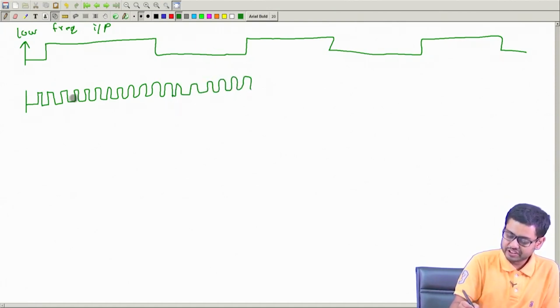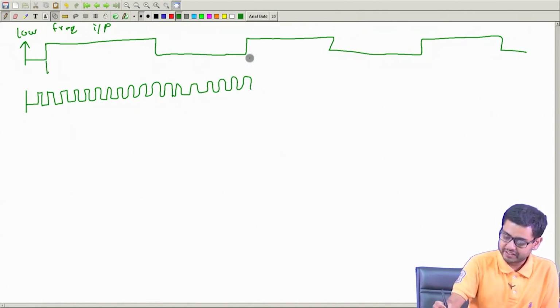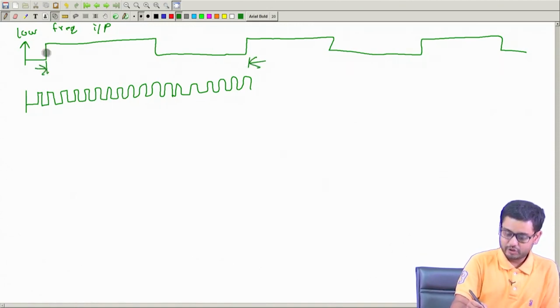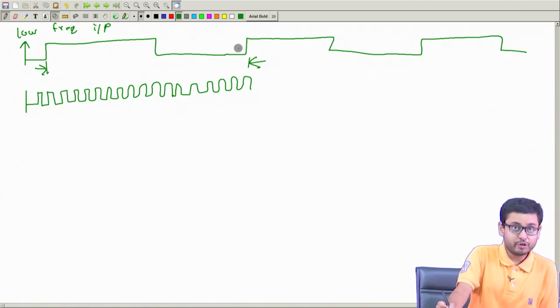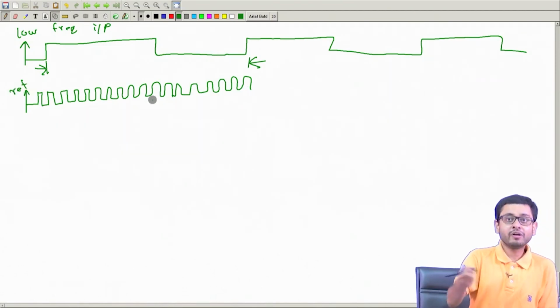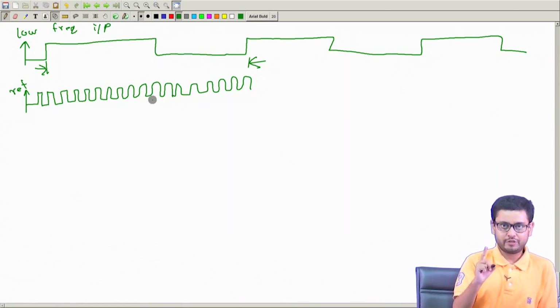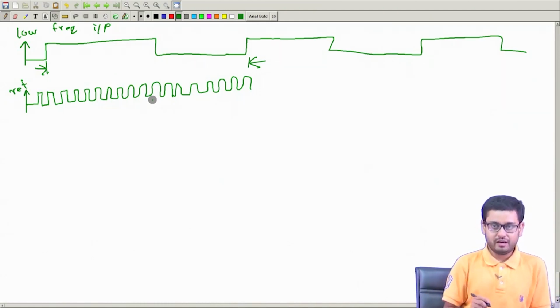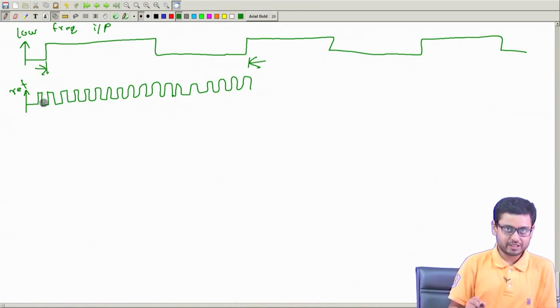Okay, and I will have a sufficient number of counts in one period, because this is anyway now a long time, input frequency is low and this is the reference signal. So, I will have more counts, and if I have one less count or more count out of many counts, that is not too much. Okay. So, therefore, reciprocal counting is the solution.